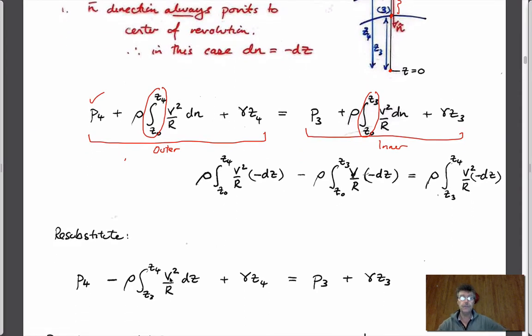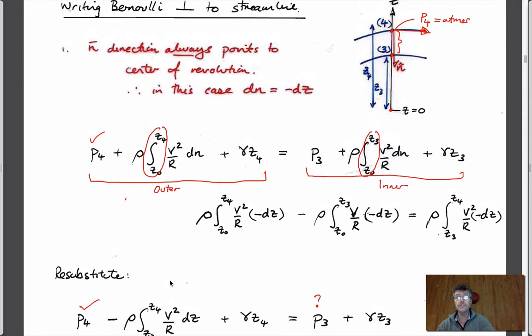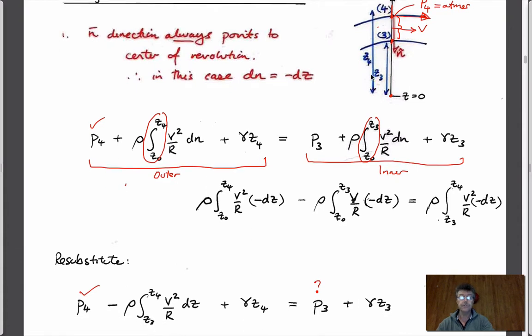And if you do that, then we end up with an expression here which allows us to calculate maybe the pressure at 0.3, which we'd like to know. If this is the free surface, this is atmospheric. If we know the average velocity along the streamlines, so in other words, we're assuming, of course, there is no velocity in this direction here because it's normal to the flow. This is the flow direction, this is zero velocity, and so it has to be this velocity. We're looking at the streamline velocity, and we're assuming that the velocities on both of these streamlines are roughly the same, and so we can take the average. If we do that, then we can calculate this component here.